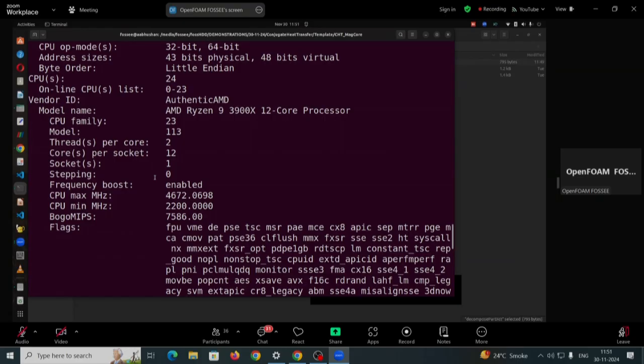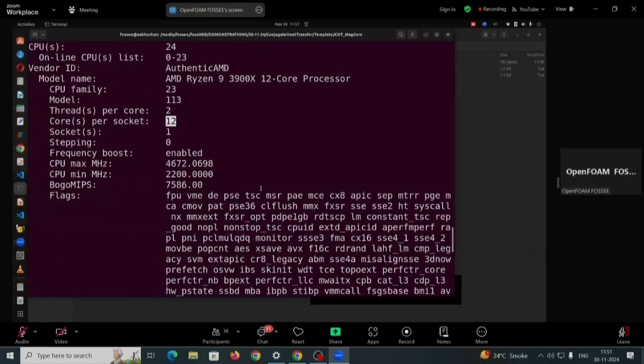So if you want to improve the speed of your simulation, I think you should disable hyperthreading. Because it is only one core that is handling the two processes, it will not speed things up. So your hyperthreading should be disabled, and you should use only the number of physical cores that are there. The other threads are not physical cores; they are kind of like virtual cores. So use only the physical core number. Yeah, thanks for pointing that out. I kind of forgot to talk about that. Yeah, so limit to 12 cores. Okay. Yeah, so I had done changes to that.